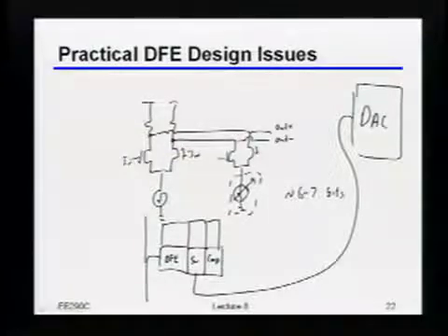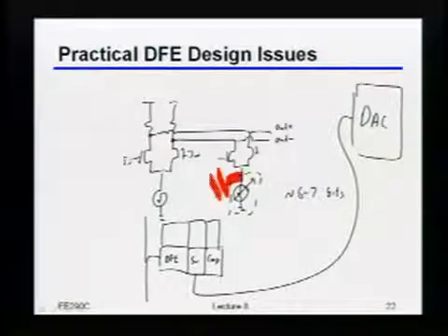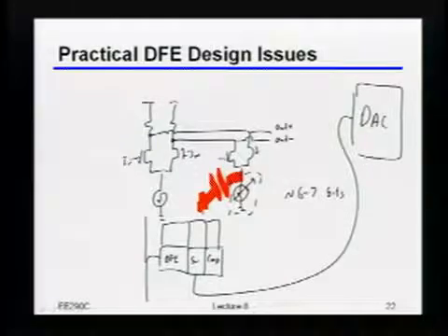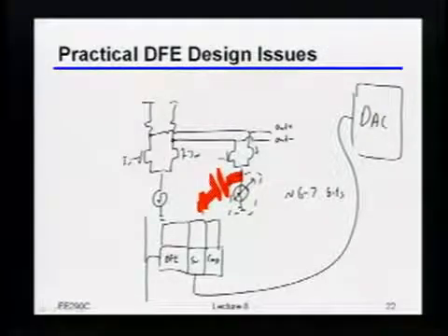The only caveat is that now you have to be really careful, because obviously there's a whole pile of capacitance on that tail node, which can cause some interesting issues. But as long as you're careful about it, this is generally how you're going to want to arrange your layouts. I think I may have mentioned this in the past: in very high-speed designs, this is the type of thing they'll end up doing.